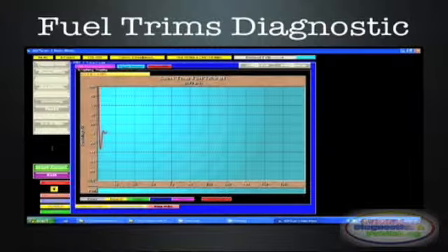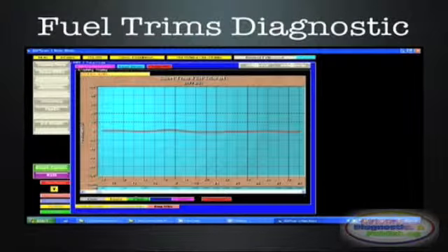After testing your O2 sensor, then you're ready to concentrate on the fuel trims. The short-term fuel trim is fast reacting, while the long-term is very slow, meaning that this PID reacts to the more persistent air-fuel imbalance. Use the short-term to check for vacuum leaks, together with any other technique, such as propane enrichment using the right tool.